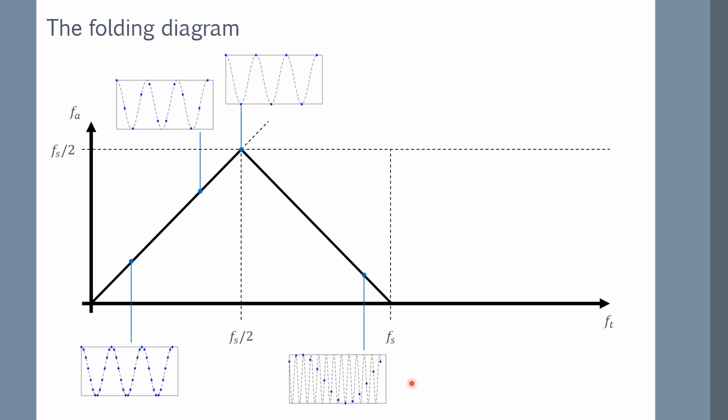Okay, so if we look here, I could show a point over here, but it's kind of complicated to understand qualitatively. So I'm showing a point where we have the sine wave showing several cycles, and you see that we get a sample every cycle plus a little bit. Because we get this slippage, just shy of or just above a full cycle, the phase of the samples is slowly shifting, and this gives us the effect that the frequency looks like the signal but in slow motion.